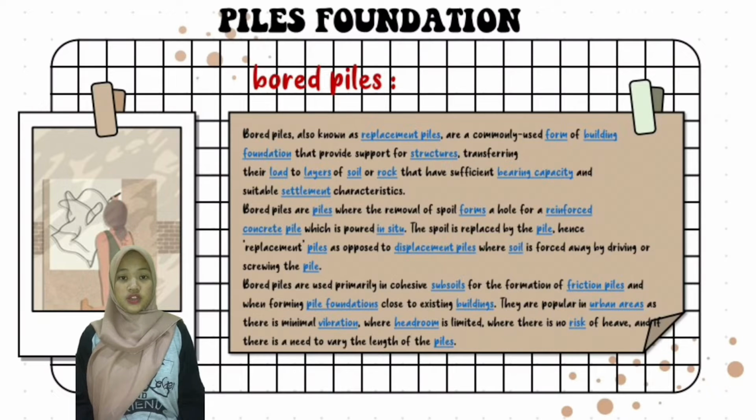Bored piles are used primarily in cohesive subsoil for end-bearing foundations and friction piles, and when forming pile foundations close to existing buildings. They are popular in urban areas as there are limited vibrations, the headroom is limited, and if there is a need to vary the length of the piles.